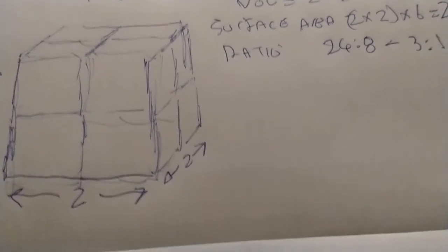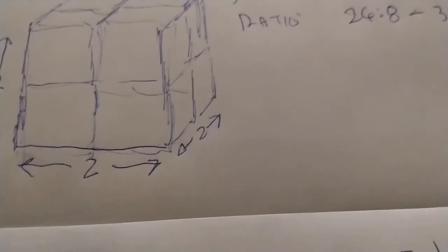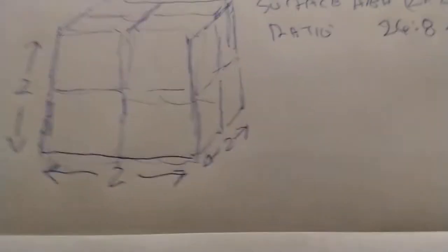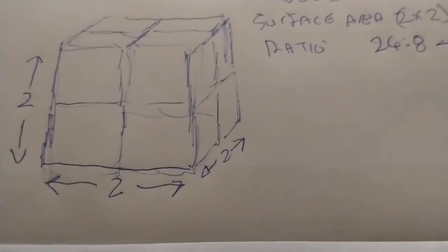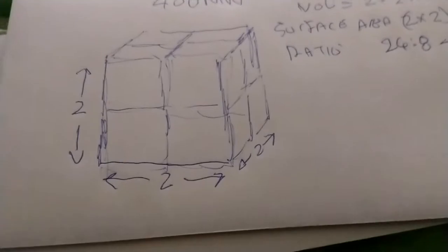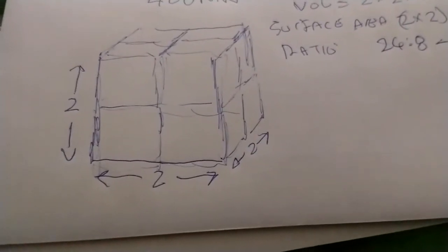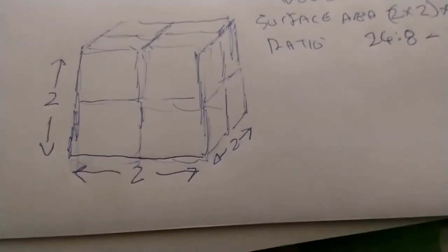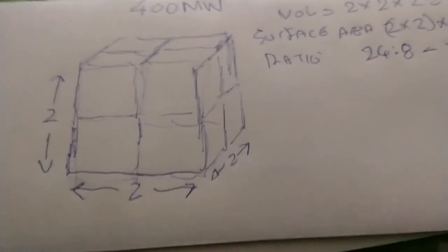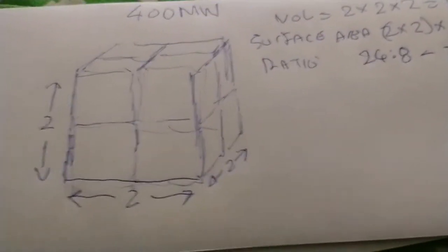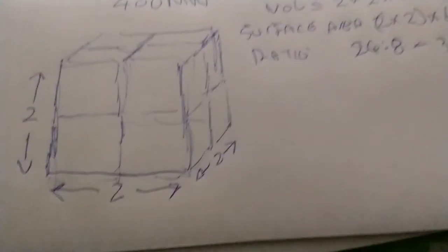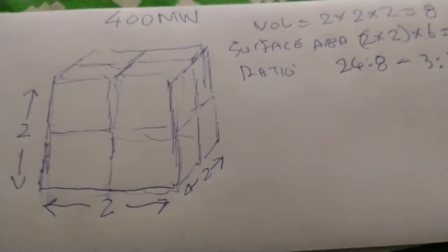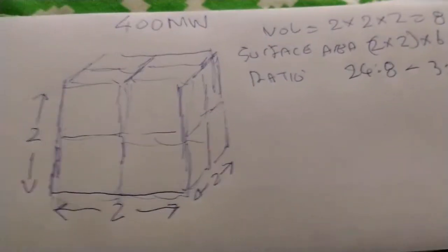So even if you want to switch the bloody thing off, you've got to pump energy into it to keep it cold. Now just think about that for a second. You've made a machine that you have to put energy into to keep switched off. So you're now totally reliant on the cooling systems to take the heat away, because the surface area of the reactor now cannot radiate it away passively. And you've now fallen into what's called in nuclear engineering passive failure mode.